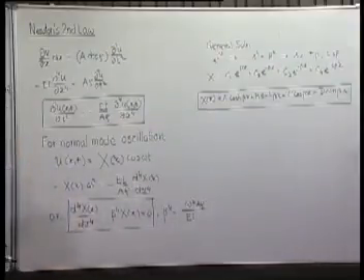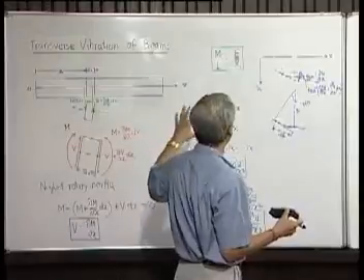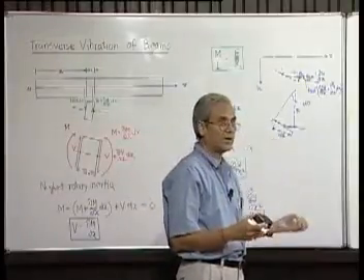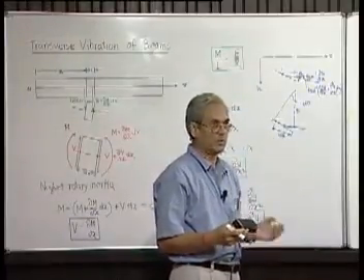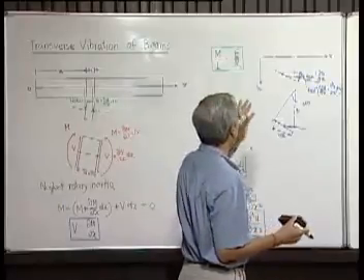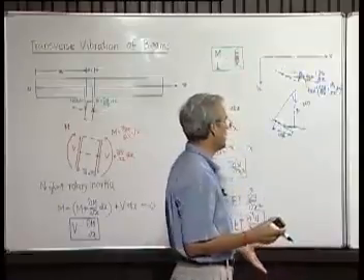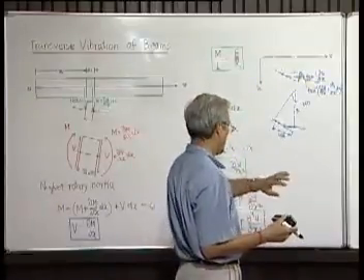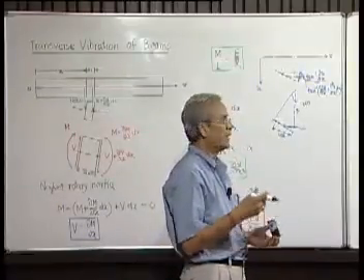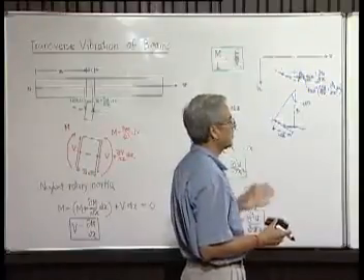In the case of a beam, boundary conditions will be 4 in number, 2 at each end. At each end you have to specify either the deflection and the slope, so there will be 2 conditions. Or in the case where it is force free, then shear force will be 0 and bending moment will be 0. We will take up this in the next presentation along with the solution of some problems.